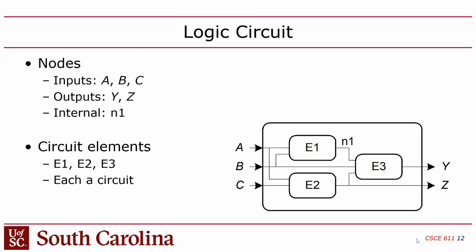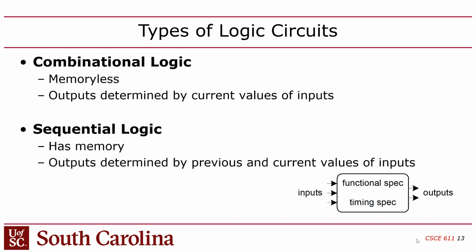Okay, I mentioned too that you've got a top-level interface with inputs and outputs. You can think of this kind of like writing a class in Java with publicly accessible methods, and then internally you have modules that are instanced in there, generally speaking, unless it's a leaf node, and then there are internal wires that are declared internally, right? Kind of like private variables in Java.